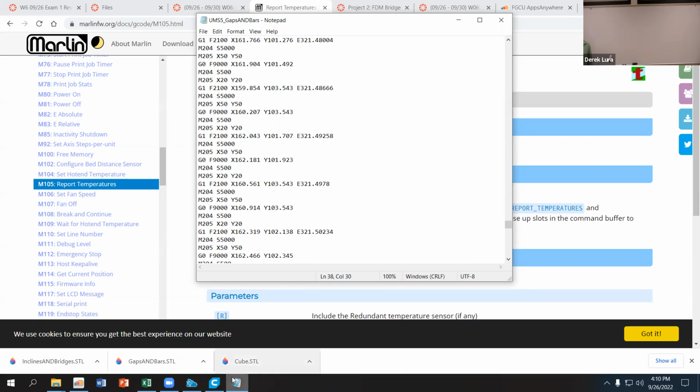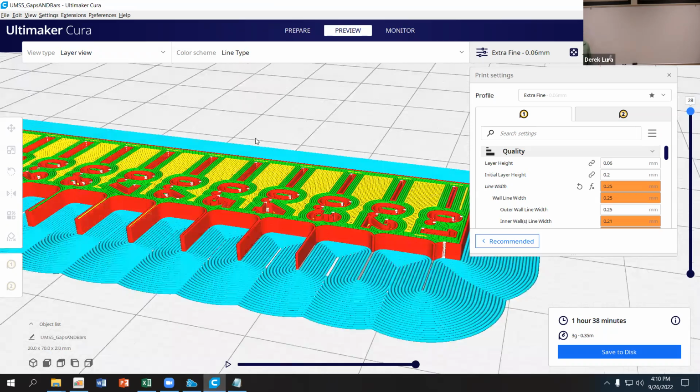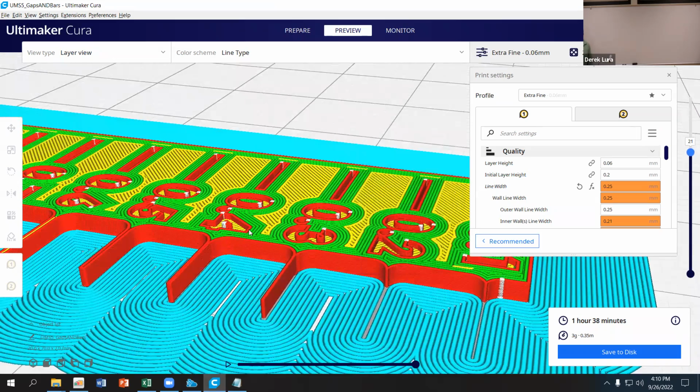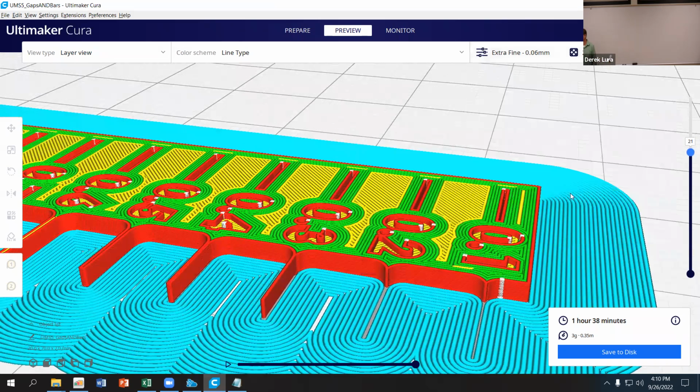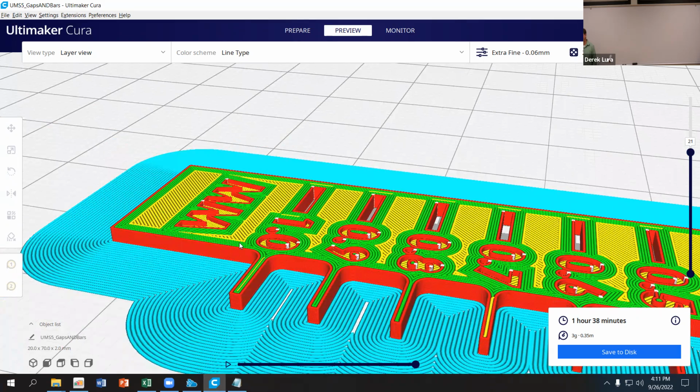And all the slicer is doing is it's taking your geometry, cutting it into layers, using that to find vertices, and then linking those vertices together in the code. So it'll go through and, if it starts here, which the start is usually this white spot, right? It's going to go to here and then go to here and then go across to here and then back down and over. And then it's going to draw an arc and then it's going to come down, over,